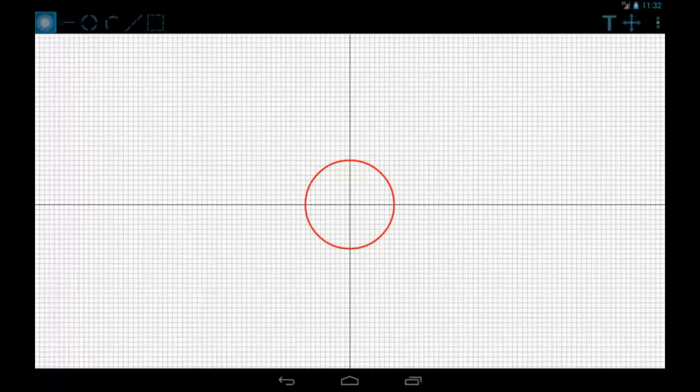First, ensure the arc command is selected. Draw a line on the screen from left to right, to determine the x radius of the arc. Then drag your finger vertically on the screen, determining the y-axis. The next movement is the rotation movement. Moving your finger across the screen will change the rotation of the arc. Note, be careful when using the arc command that you draw it in the position you want, as moving and selecting arcs are not yet supported.